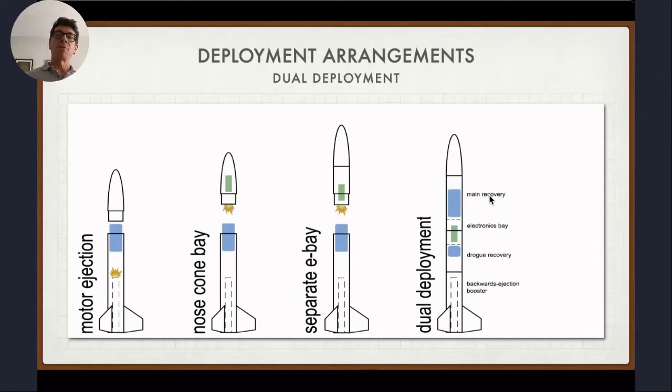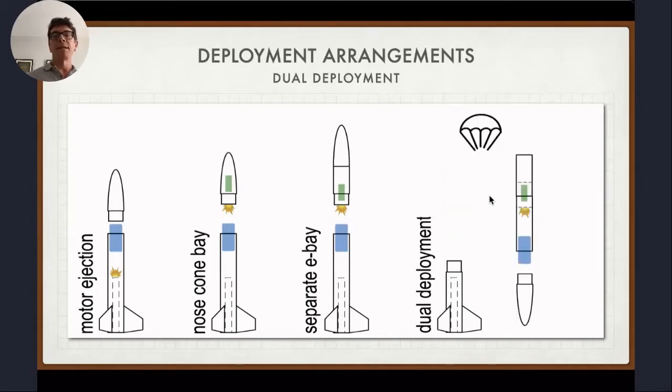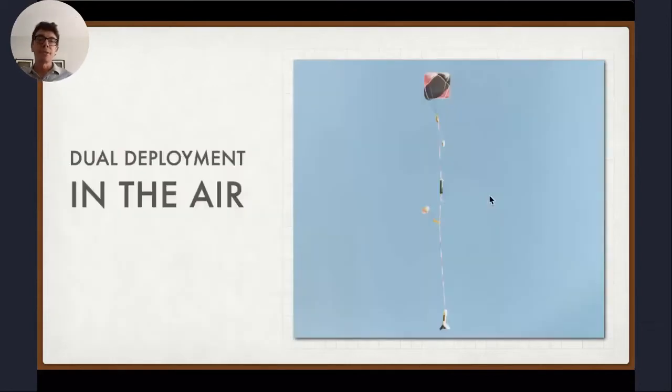So here is the rocket prepped. At apogee, it separates. The drogue parachute comes out, and then it descends quickly. And at the low altitude set point, the second charge fires, the main parachute comes out and brings the rocket down gently, but not drifting too far, because it's only coming down under a large parachute for the last little bit. So this is how it should look.